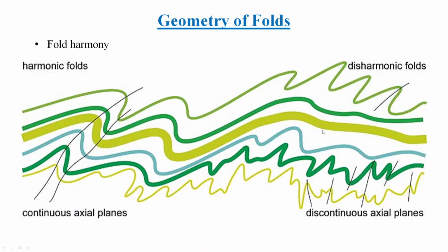So here is an example of a normal fold. Here, this one is an example of an overturned fold, where one of the limbs has rotated more than 90 degrees from the start of the deformation. Earlier there was a layer which had been folded into a normal fold. Already you can see there is a rotation of about 40 degrees, 60 degrees, 70 degrees, whatever it is. Now you are rotating it further. So finally, if the rotation exceeds 90 degrees from its initial stage where it was a horizontal or planar bed, in that case it will be considered an overturned fold.